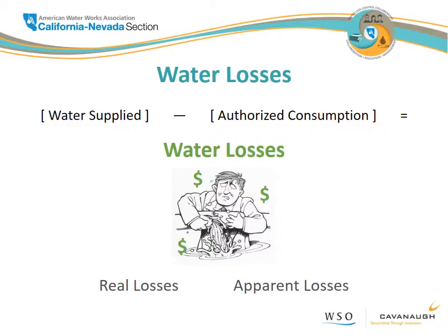It's now our job to break water losses down into the component parts of real losses and apparent losses. As you know, a total water loss volume is instructive in that it's a measure of water that is not generating new revenue, that is not put to authorized use. But beyond that, it's going to be much more useful to understand which types of water loss are happening in your system. And to do that, we have to do a bit more poking and prodding to understand and categorize apparent losses apart from real losses.